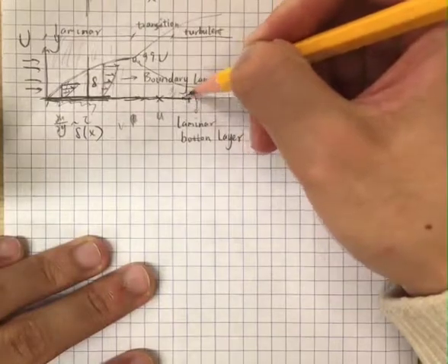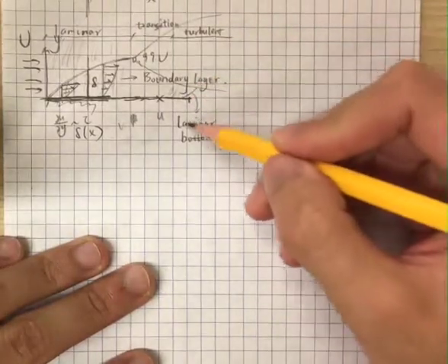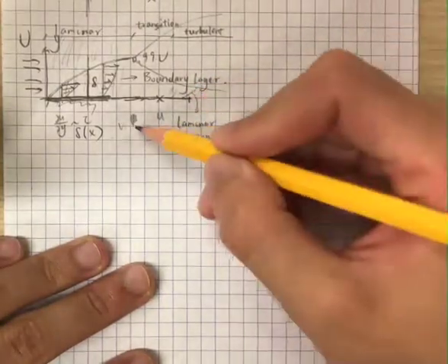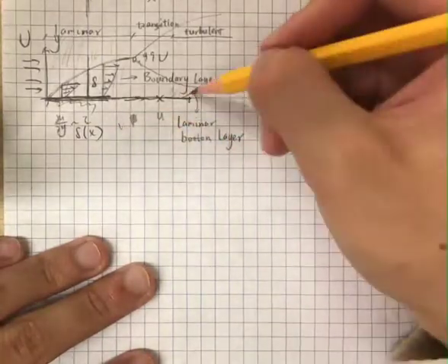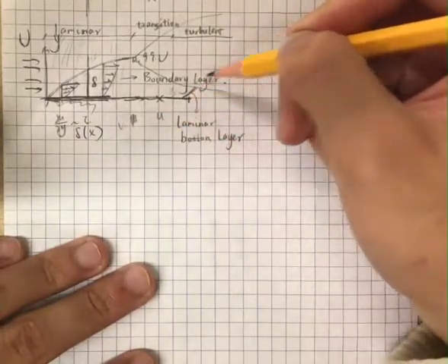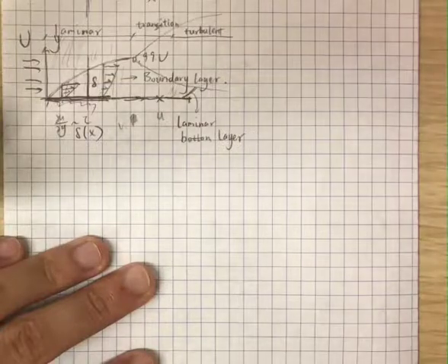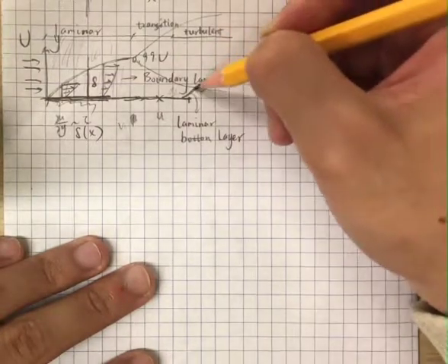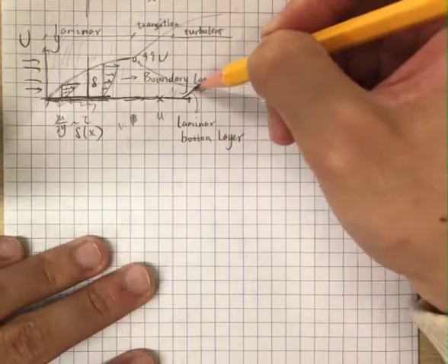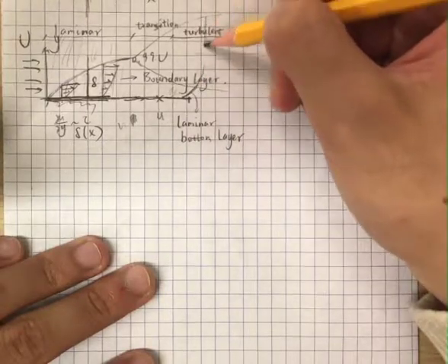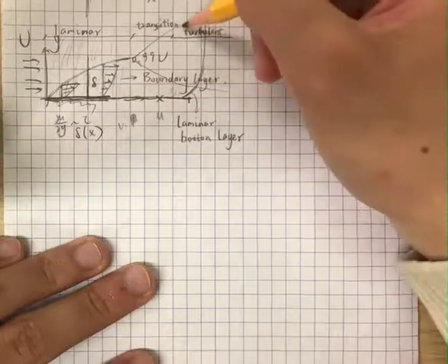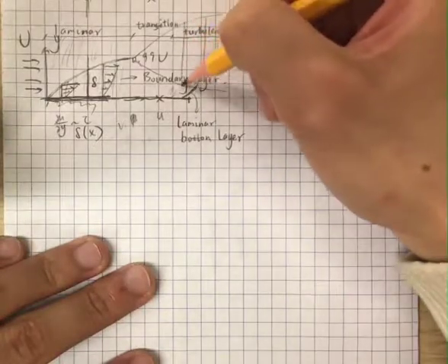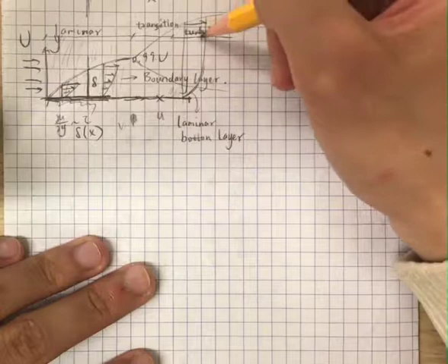Here, in the laminar bottom layer, the tau is still notable, right? So here we would see a relatively large velocity gradient. But up here, in the turbulent region, the velocity change may be less. So we will see something like this.